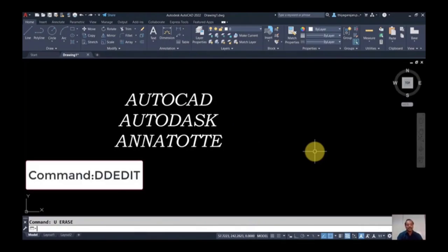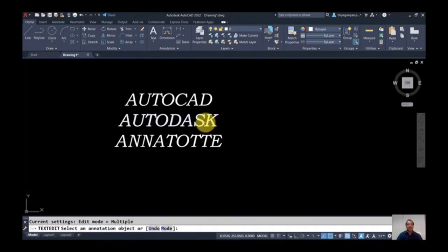So there is a command called DDEDIT. Just select the text line which you want to edit, and go and type whatever you want. DD means display dialog box of edit.